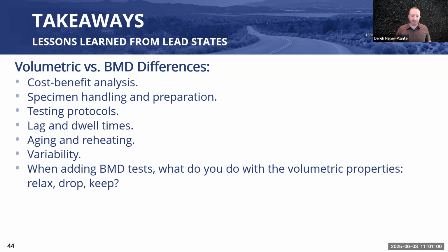Balanced mix design tests are showing key differences there, where most have found that the contractor can test specimens hot, out of the plant, and the agency could test two days later, right? Not have significant differences with many of the things that we do today. Balanced mix design is showing a clear difference: the act of reheating, conditioning differences, specimen handling, and how they're prepared are making larger differences than we're currently accustomed to. So where we've maybe had flexibility in the past, we may need to think about how to change that so that we can match up between the different parties involved in production.